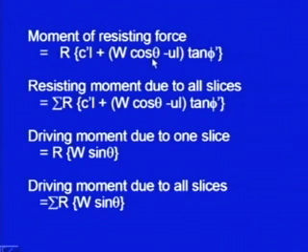In fact, here theta being taken negative or positive is not going to matter, but it will be affecting our next point. So, this was the resisting moment. Now, let us calculate the driving moment. The other component, W sin theta, is the component of the weight which is acting tangentially to the failure plane.